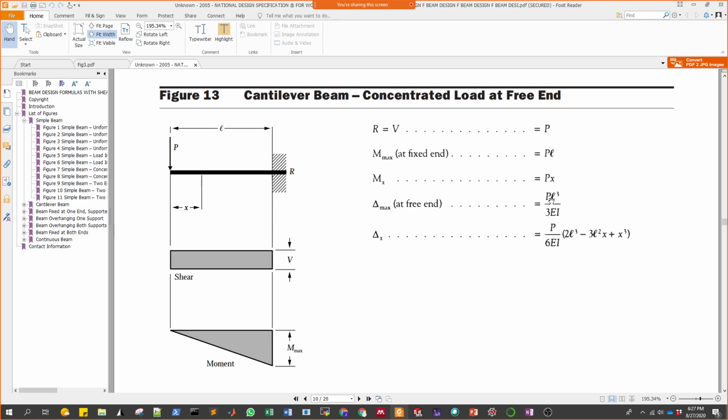Now there are different ways in which you can solve this problem. The first one is you can use beam elements, or you can use 2D plane elements, the plane strain or plane stress, depending on which boundary conditions you want to consider, or you can do the 3D model and simulate this with 3D elements. For this tutorial, I'm gonna do the 2D plane strain elements.